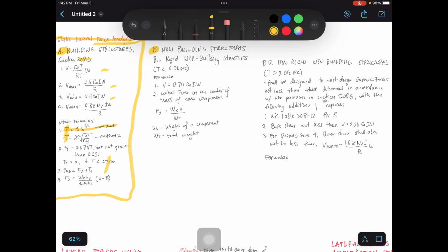So, number 2 formula is, yun nga, kukunin yung top na force, lateral force, yung pinaka mataas na force. Kung meron kang rooftop, so lalagyan mo siya ng FT, if your period is greater than 0.7. So pag less than 0.7 ka, 0 na yung FT mo. Pero kapag equal or greater than, kailangan mo kunin ang FT and ilalagay mo yan sa rooftop mo.